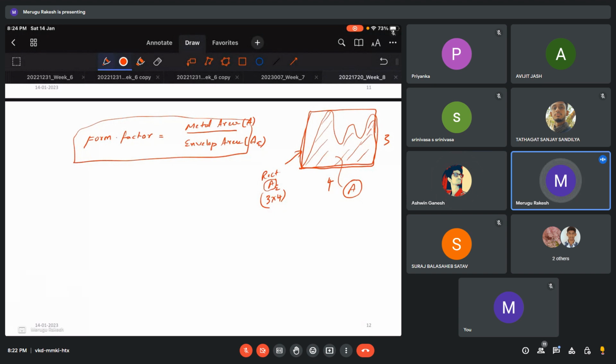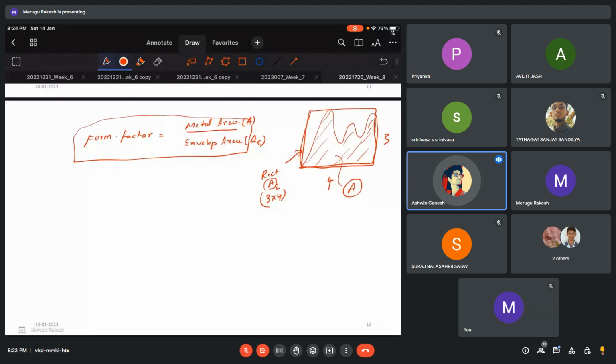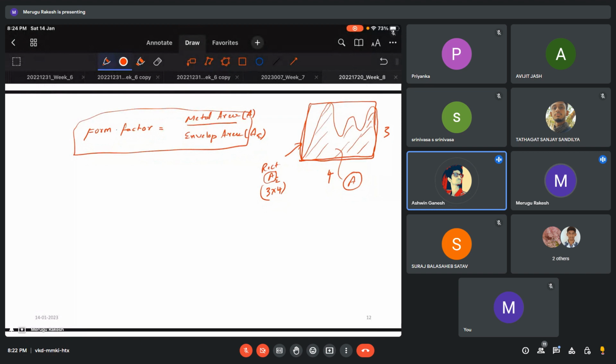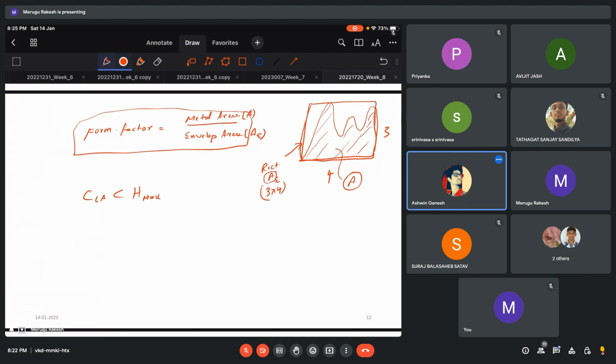Which means Rt is greater than Ra, and last class you told us the order of which is larger, which is smaller, like RMS. Comparing the maximum peak and minimum valley with the center line average, the maximum height means here Rt only, no? Yes, Rmax. Which means the center line average is 1/4 of Rt, no, sir? Yes.